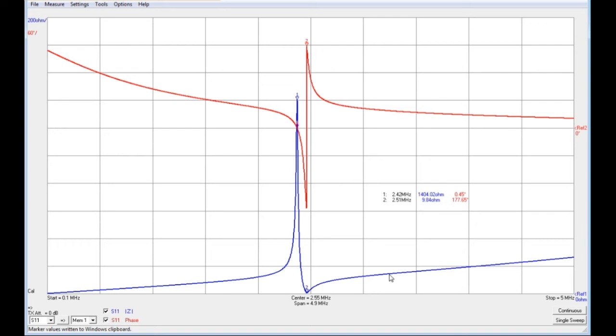So here we are coupling to the secondary coil, and it's a secondary coil resonance that we're looking at here, seen through, reflected into S11 and hence Z11 into the vector network analyzer. And this is very characteristic. It's almost like you have a parallel point and a series point for that resonance, very much similar to what you get with a crystal resonator, which has both a parallel and a series resonance. So we have that high impedance peak at 2.42 megahertz and 1.4 kilohertz is the peak. That peak would no doubt be somewhat higher than that. We'd have to take a much narrower scan to find out what the height of that peak might actually really be. And then we have a series point down here, which is in line with the phase change.